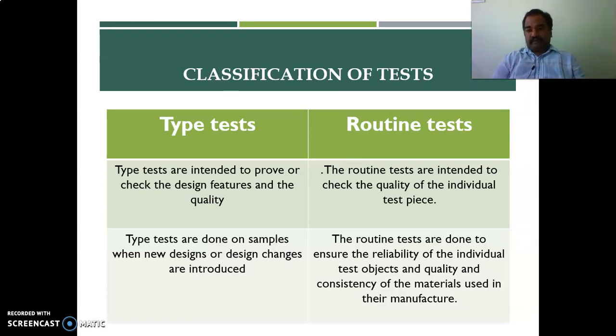The testing. So the tests which are conducted on high voltage equipment will be of two types broadly. One is a type test, the other one is a routine test. So if you bring up a new design, then a sample item of that new design will be tested to check for the quality and also the design features. So the tests which are conducted to check the design features or the quality of the design are called type tests, and they are exclusively done on samples, not all items of the design.